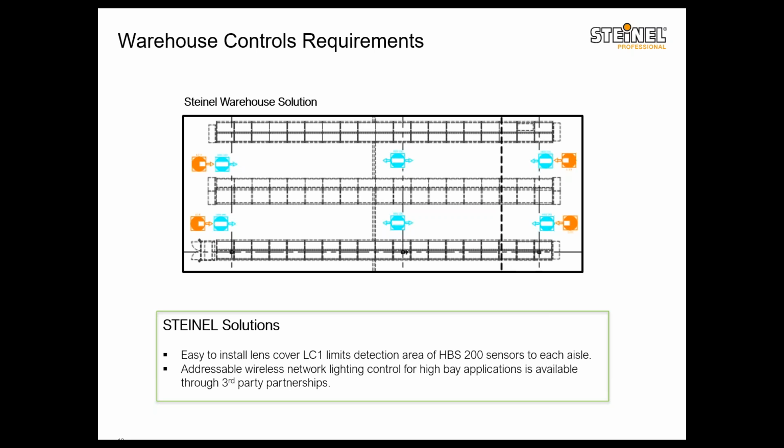Poria, we do have a question about the warehouse requirements. Do the new high bay requirements have timeouts just like an office space? Like after 20 minutes, the lights have to dim to a certain percentage? Yes. The new time delay applies to everyone across the board.